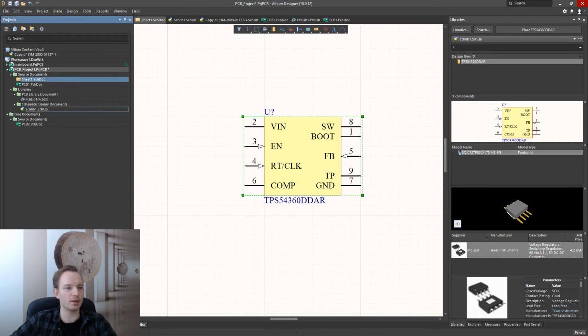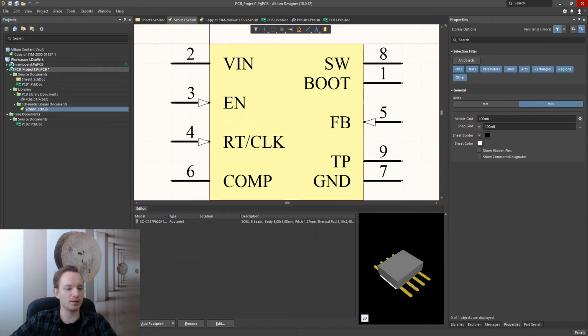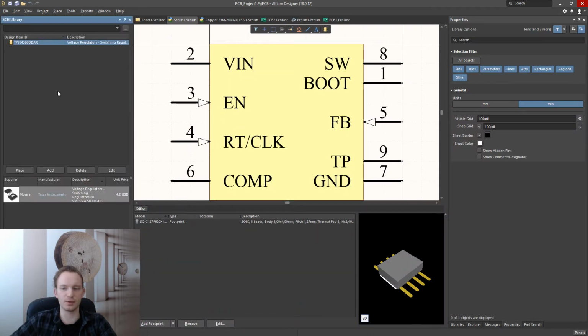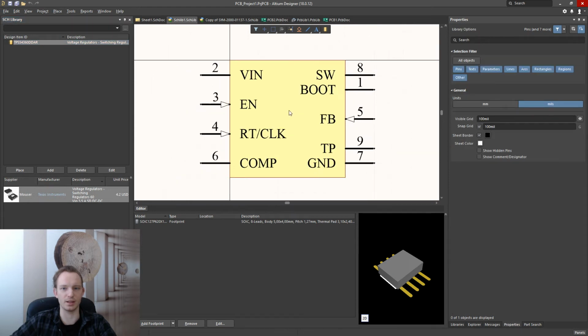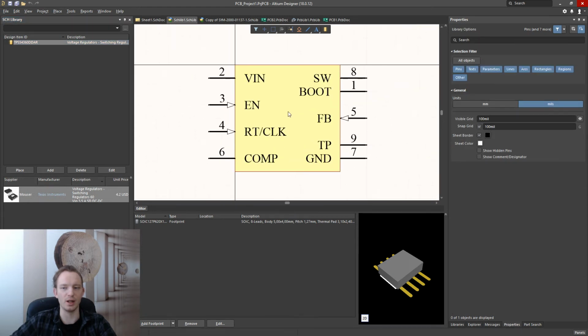And what I would typically do then is that I would do the same thing even for resistors and capacitors, because the useful thing about creating a separate component for every distinct part that you have on your schematic is that you can then export it into the BOM, and you can get the distinct product ID codes directly in the BOM, which is very useful. So like using a generic resistor is not going to give that.